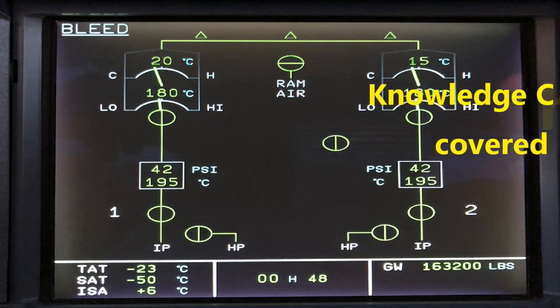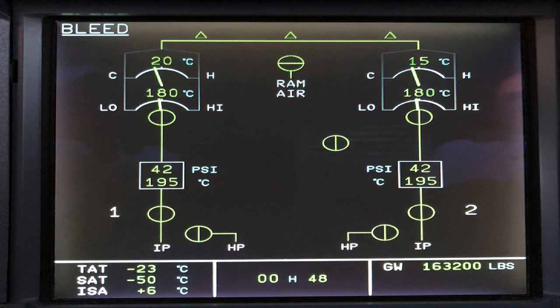We are now on to session 2, and this is identification of the components, the functions and locations of the pneumatics system. So I'm going to go ahead and start with the bleed air Precooler exchanger, and then related parts to the exchanger. You have an exchanger, and that is just cooling. Obviously, it says Precooler, so you know it's cooling that hot air that's coming from the engine compressors. And there's going to be some monitoring of that with certain other components. But that's what it's for. It's basically exchanging the heat so that it's cooling that air coming from there.